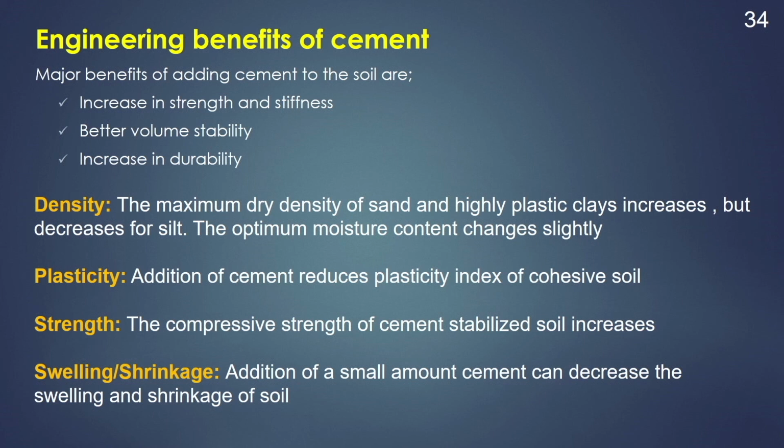So, the major benefits of adding cement to the soil are the increase in the strength and the stiffness. Then better volume stability, that means it will reduce the swelling and shrinkage tendency of the soil, and increases its durability. If we look into the density, then the maximum dry density of sand and highly plastic clay will increase. However, for silt it will decrease. Similarly, the optimum moisture content will not change significantly due to the addition of cement.